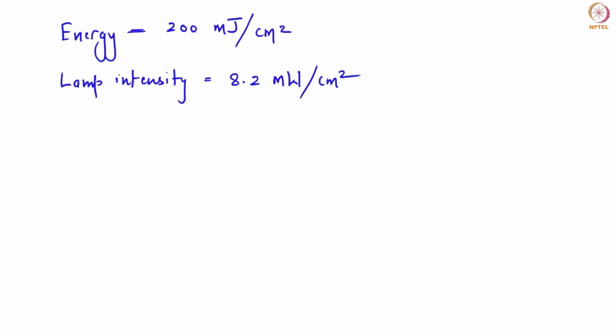Whenever you're using a certain type of photoresist, these resists will come with what is known as data sheets, especially when we are talking about the negative tone resist. Then we often have data sheets that are provided by the vendor, and in that data sheet you will often have this information for which thickness what is the energy that is required.